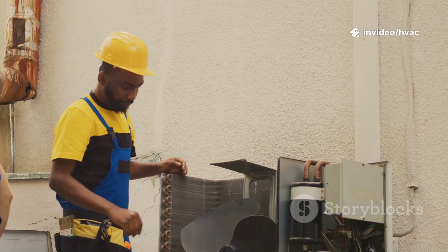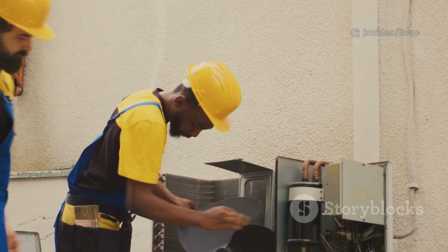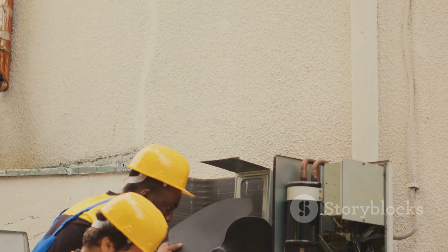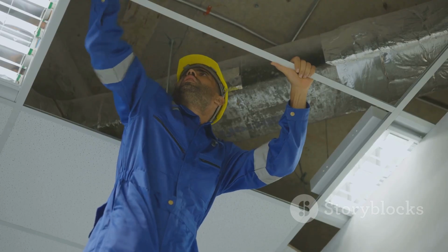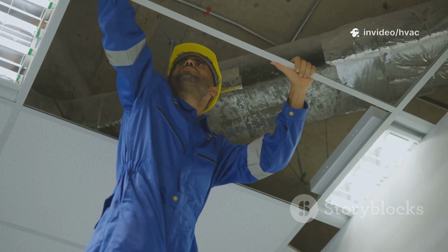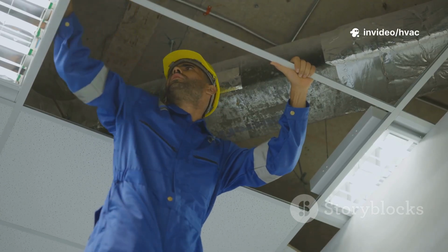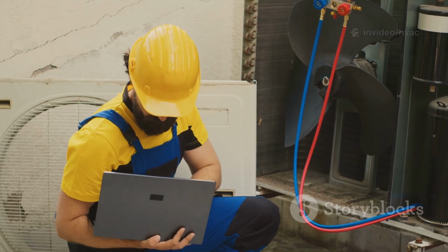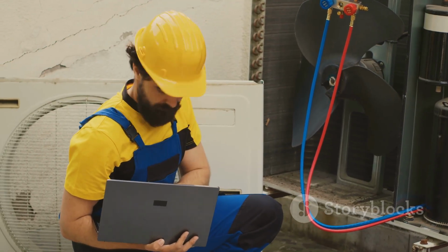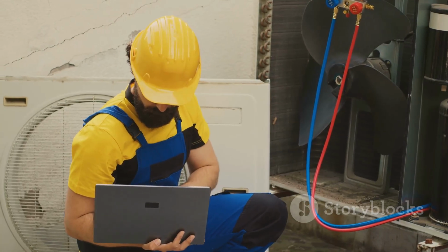You'll also want to create several bends or zigzags with the sensor as you install it. Typically, you should plan for at least 3 to 5 bends depending on the size of your duct. These bends help the sensor sample air from different parts of the duct, giving you a more accurate average temperature. For rigid rod sensors, make sure the rod spans as much of the duct width as possible and is mounted securely to avoid vibration.